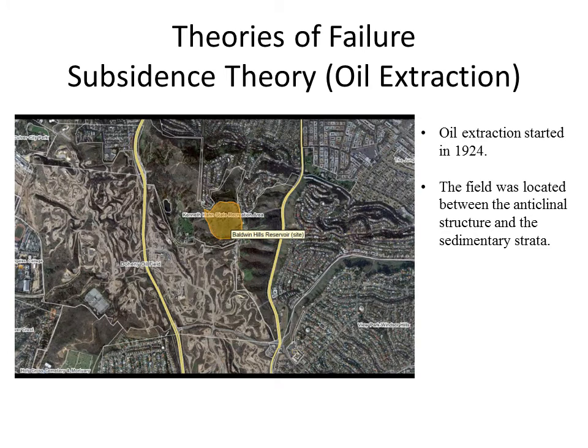The second theory is the subsidence theory. This subsidence came from the oil extraction, which started in 1924. Supporters of the subsidence theory argue that the 6 feet or more of ground subsidence in the Inglewood field is related in space and time to the net withdrawal of the 67,000 acre-feet of oil, water, and sand from the shallow producing horizons. The oil field occupies an irregular oval area that extends diagonally across the trend of the hills along the axis of the faulted Inglewood anticline.